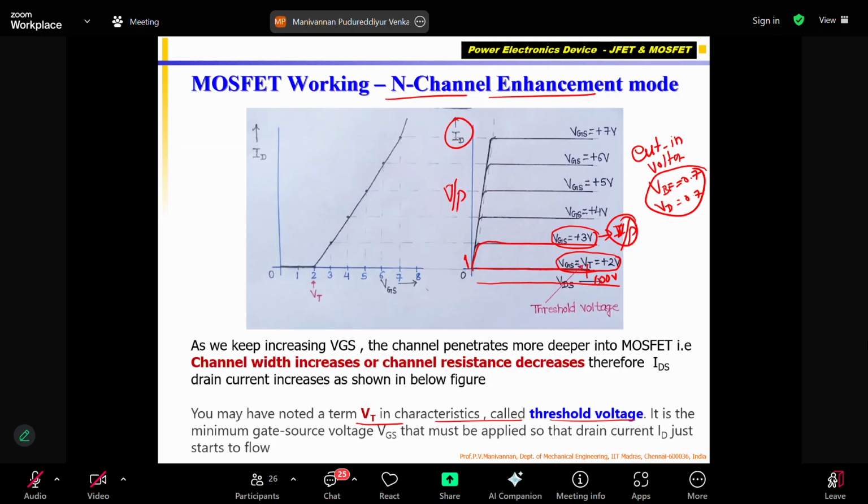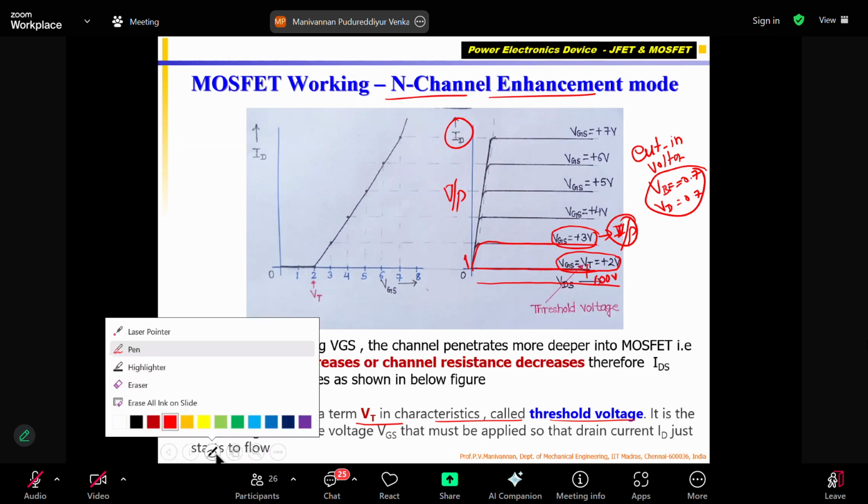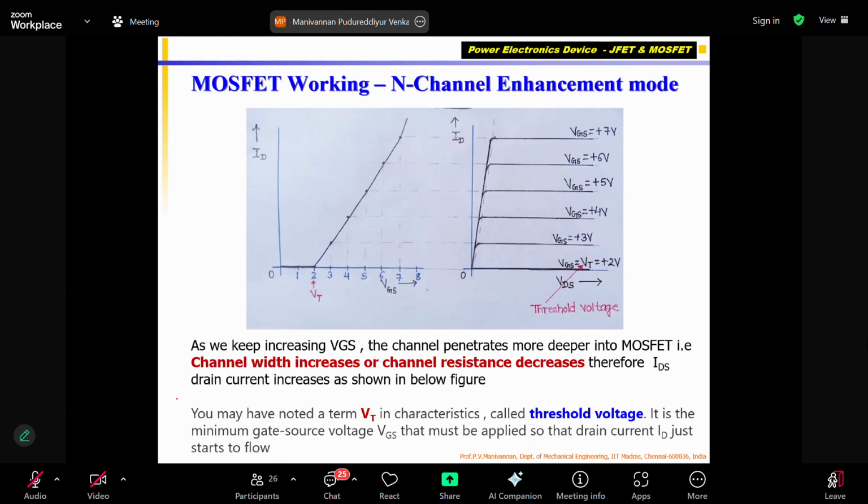Similar to that, if it is a MOSFET, enhancement mode, N-type or P-type, there will be some minimum voltage, say 0 to 1 volt, up to which the current will not increase, whether P channel or N channel. Output will not come. That voltage is called the threshold voltage. That is what is shown here, correct? In the exam, sometimes you are asked to explain how the N-channel MOSFET works, with input output characteristics, so you need to draw these curves by hand.